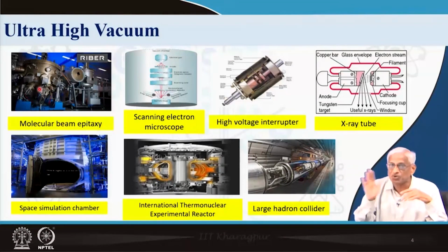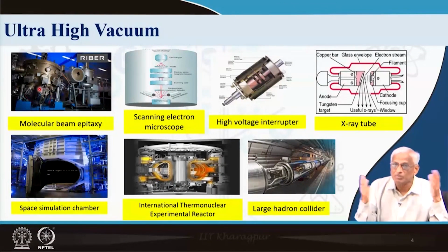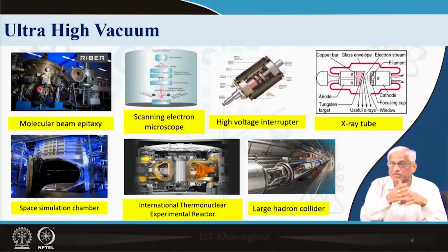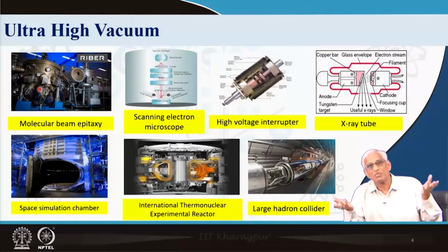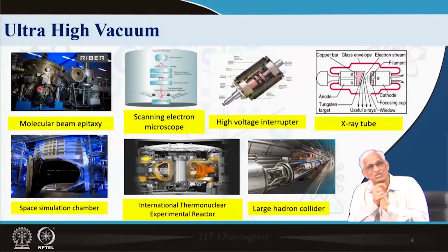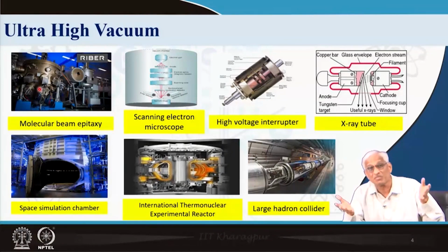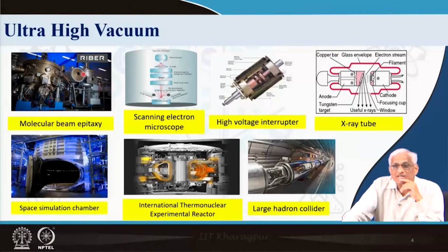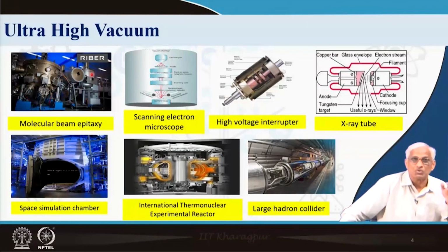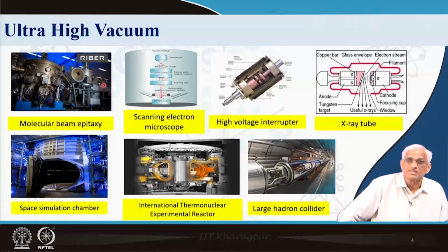So, if you finish it more and more like submicron finish, it will be better. And if you do not finish, lot of degassing will come, which will interfere with your vacuum conditions, and you will not get your proper film. There will not be electronics, there will not be space technology and nuclear. So, the processing of chamber technology is also very important in molecular beam epitaxy unit. This we will again discuss in thin film depositions and coatings when we go for applications.